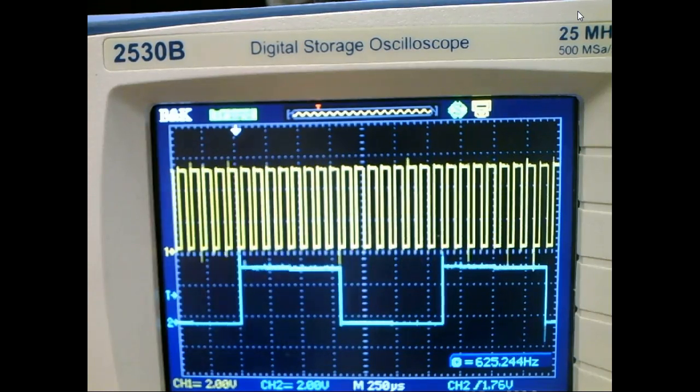So if you start them on the same thing, it's okay. It's just that for here, how far does your scope go up? Don't they give you counts on the top? They give you 15 on the top. Yeah, but we won't quite get there because it's actually 16 pulses. You won't be able to. Yeah, the last one will stay low. You won't see it go back high because it's 16 pulses, so they didn't give us enough pulses.